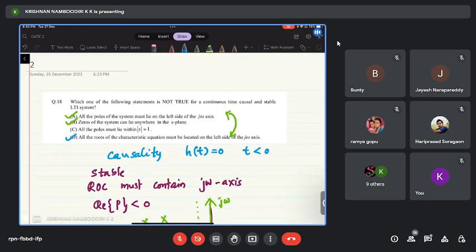So why is this modulus of s coming? This is the incorrect one, so the answer to the question is option C. Why is modulus of s coming here? This is here to confuse you regarding Laplace transform and Z transform. I will deal with Z transform in one of the coming classes if I have some questions to solve. If you consider discrete time signals and Z transform, you will see modulus of z coming into the picture. But here we are considering only continuous time signals, and in Laplace transform, modulus of s does not have any role. So don't get confused by that.